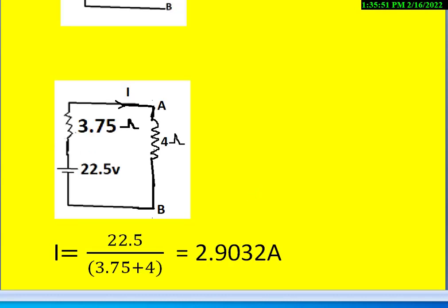So in the Thevenin's based problem, there are only two parameters to be calculated. One is Thevenin's voltage, the other is Thevenin's resistance with respect to the terminals A and B with AB terminals open. So when the load is connected between A and B terminals, the current also can be found using the Thevenin's equivalent circuit like this.